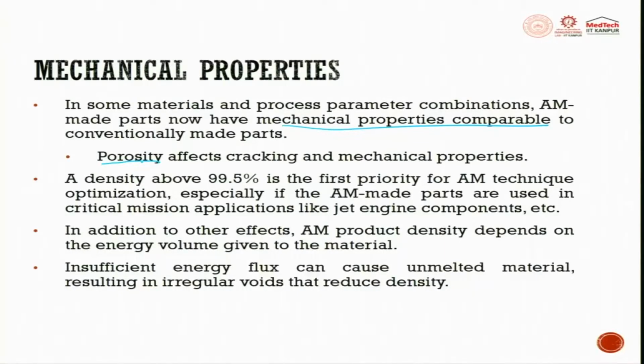non-destructive testing methods. Once you establish the process, you evaluate the part through non-destructive testing in order to figure out whether any porosities are present or not. These porosities can be on the surface, between the inner surface and outer surface, or in the inner surface also. So porosities affect cracking and also reduce the mechanical properties.